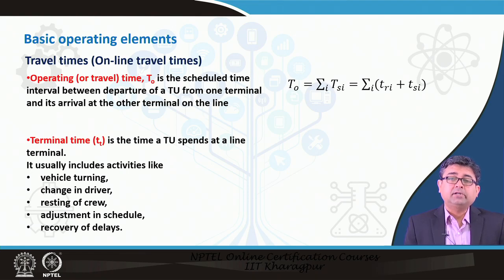We have to remember that labor laws apply. So, we have to give resting time to all the crew, the drivers and the conductors on the line. So, there is some resting time involved, and adjustment in schedule. Maybe the vehicle has arrived ahead of schedule or is late on schedule. How do you adjust all those schedules for the next run to begin? That is all taken in the terminal time, and recovery for delays as well. So, terminal time is the time that a transit unit spends at the line terminal, at the two terminals at the end.